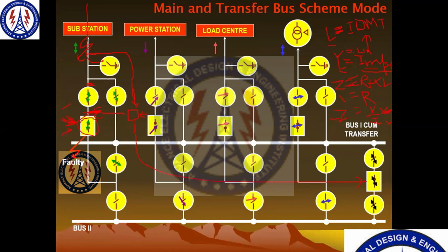And when this isolator is in power, the system automatically understands that this is out of the system and this circuit breaker is in the system. So in that case, we have to wire the cables of this circuit breaker to this relay again. So when this isolator is on, we will give the contact of this isolator in the logic, or when we create the bus bar scheme logic.